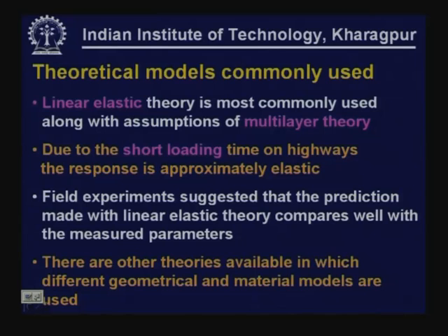So, for such small load pulses, the behavior of the pavement is generally observed to be elastic. Most of the deformation is normally recovered, although there is some irrecoverable component of deformation. So, that is the reason why most of the agencies use linear elastic layered theory for analysis of flexible pavement.